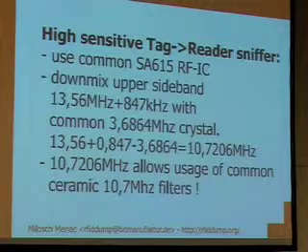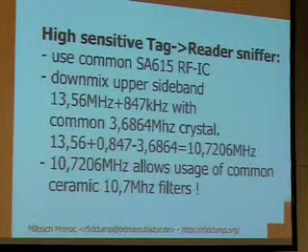What we didn't want is to buy expensive antenna equipment. You can't use the existing electric antennas, you need a magnetic loop antenna. Magnetic loop antennas are awfully expensive, but we found out that's only because of one thing. The point is that the magnetic loop antennas you can buy freely are used for sending also. You need very expensive adjustable capacitors for this kind of antennas because we have very high voltages when sending.